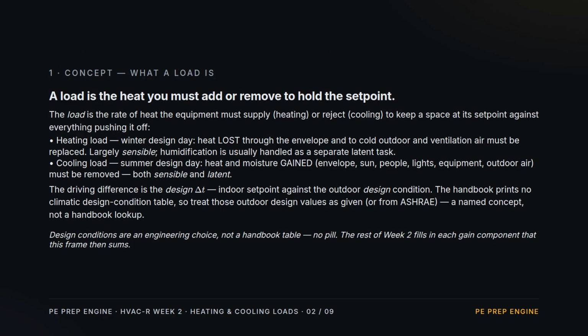A load is the heat you must add or remove to hold a space at set point. On the winter design day, you replace heat lost through the envelope and to cold air, mostly sensible. On the summer design day, you remove heat and moisture gained from the sun, people, lights, equipment, and outdoor air, both sensible and latent. The driving difference is the design delta T, indoor set point against the outdoor design condition. The handbook prints no climatic design table, so take those outdoor values as given.